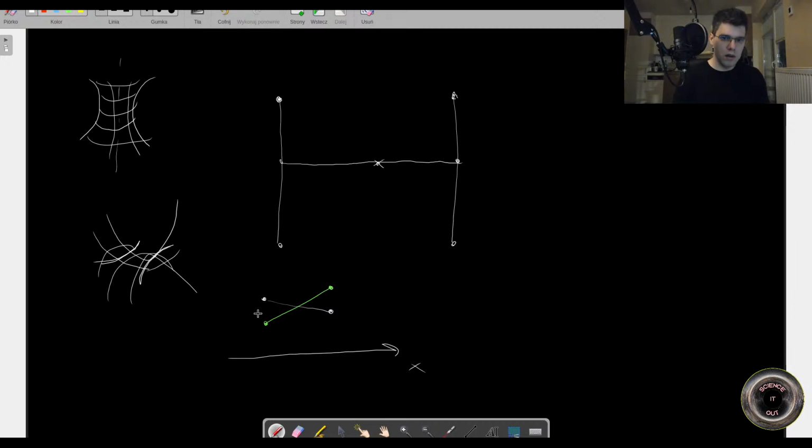So here the ray was above the terrain, and here the ray is below the terrain, which means we had an intersection somewhere in between. And then what the program does is, again, it does a linear interpolation, and it finds the intersection, assuming those are connected with straight lines. So that's how the intersection point is calculated. And then the position and elevation of this point is taken, and it is used for further processing. So that's how the terrain works.